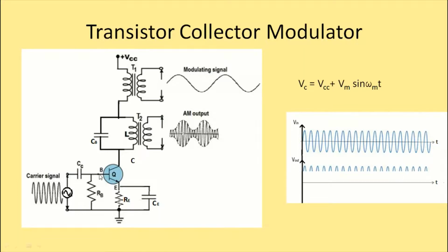So now, when compared to all the previous conditions of biasing, the current biasing voltage is at the maximum. It is at VCC plus 5 volts. So, for this maximum biasing voltage, the collector end will have the highest amplitude spurts. And because of that, the sine wave generated here will also have highest amplitude. So, we reach this positive peak.